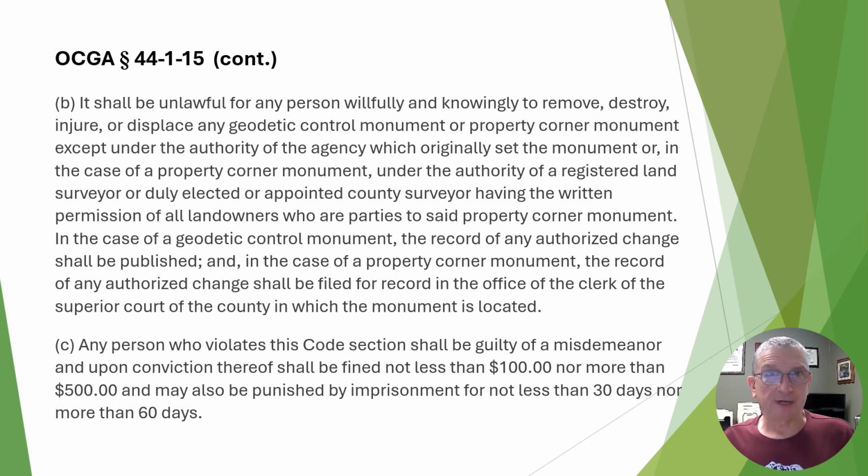The one time that I've seen something like that actually happen is when some neighbors decided they were going to regrade an area to make for better access from a road. They're going to cut a big bank down. The pin was up on top of the road. We didn't even have to go remove it. The bulldozer did that for us. We replaced it where it was by using angle and distance from the same control. That was an action that was cooperative between the two property owners.